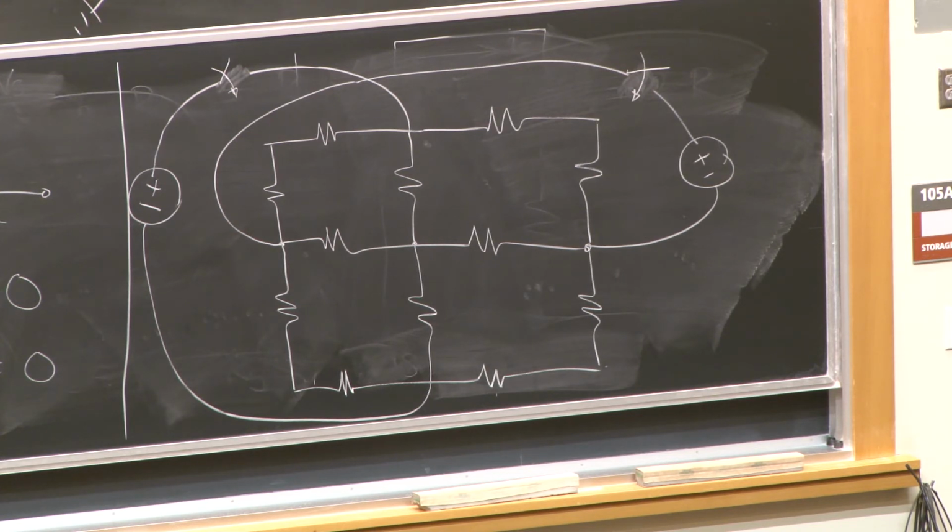Cool. So any questions on this? By the way, yeah? Excellent question. So the way that you'd measure the voltage in the lab, you can use a voltmeter. So that's just a piece of equipment that you have. And I think you'll get to play with that in lab on Wednesday and Thursday. You can also use, most microprocessors, like the one that you have, actually has what's called an analog to digital converter, which takes an analog voltage, like the one that you'd generate with this kind of circuit, and turns it into a digital code. You've actually already used that. So that's what you use to measure the voltage across the resistor in the imaging lab. It's an analog to digital converter, yeah.